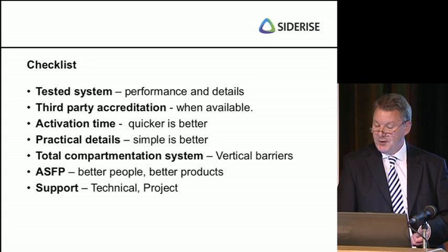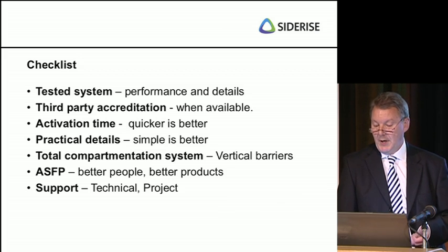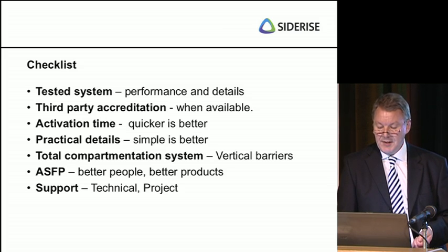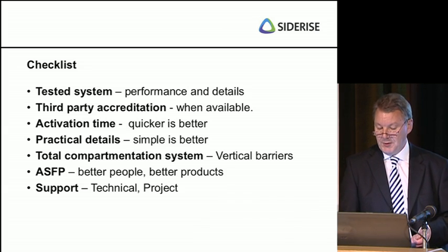Activation time to full seal closure is important. Quicker is better. Consider the material form and installation details. Simple concepts result in practical details. Is it a total compartmentation system? Are vertical seals available from the same supplier?